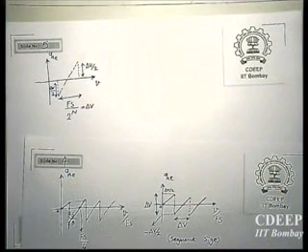If this is the case, then I have an approximation to be able to calculate the RMS value of quantization error. Because if it is not, then it is dependent on the signal, and I cannot calculate the RMS value of quantization error independent of the signal. We just make this assumption to be able to calculate QE as an independent function of V(t). This distribution is possible to get from hardware also.